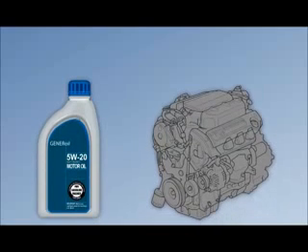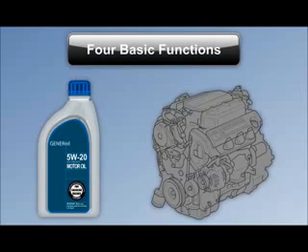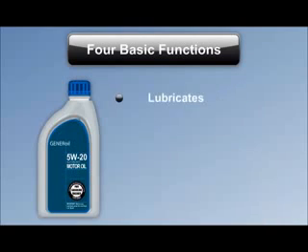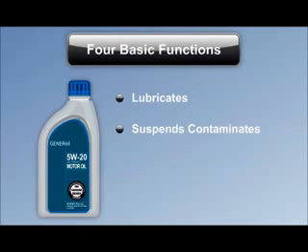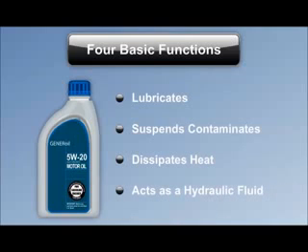Oil plays a vital role in engine operation and lifespan. Engine oil's four primary functions include lubricating, suspending contaminants, dissipating heat, and acting as a hydraulic fluid for internal engine components. Lubrication represents oil's primary function.